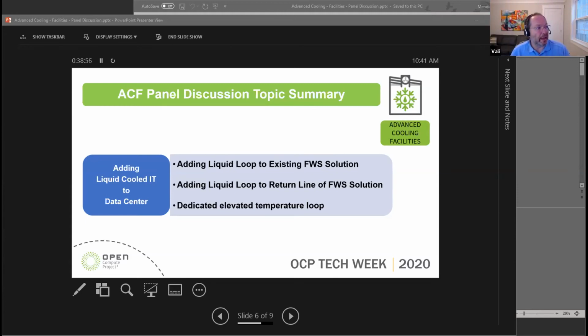But let me also add to what John was just saying, because I just happened to have been looking at some notes from an ASHRAE winter conference of 2020. John, I think you were there, and I think one of the thermal architects that we both rely on very heavily actually presented this. So he's got, for a certain class of CPUs, starting initially from 75 watts, going up to 600 watts. And at the 75 watt range, it's perfectly acceptable to use A4, which gets, I think, close to 35 C entering air temperature. Correct me if I'm wrong. Like I said, I never remember the limits of that.